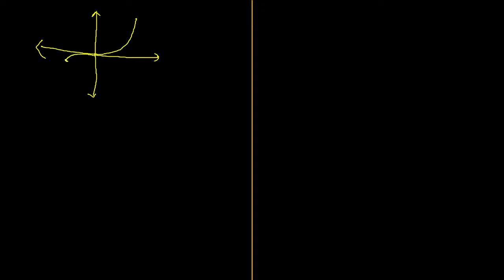Yes, the negative bias ends here. If you go beyond this, the diode will get damaged. Our PN junction diode will get damaged, not our Zener diode. Zener diode will operate in this region, you all know, right? It can be operated in 3 regions, but our normal power diode can be operated only in 2 regions. This region is called the reverse bias region, and that is called the forward bias region.